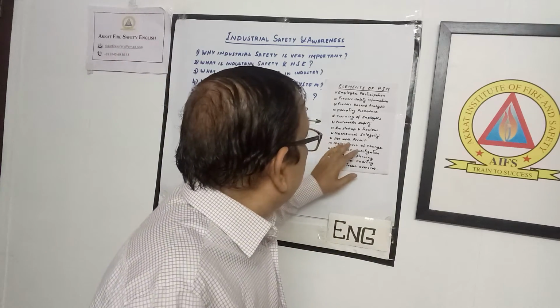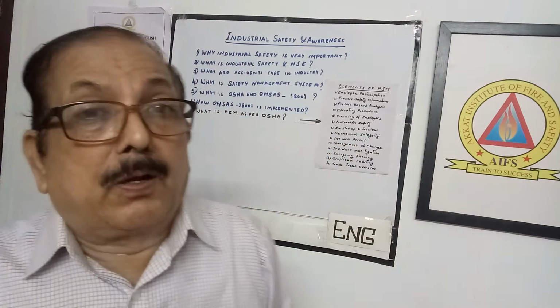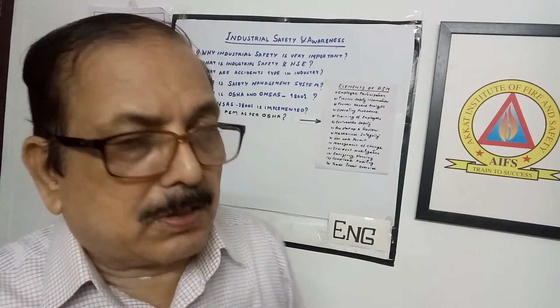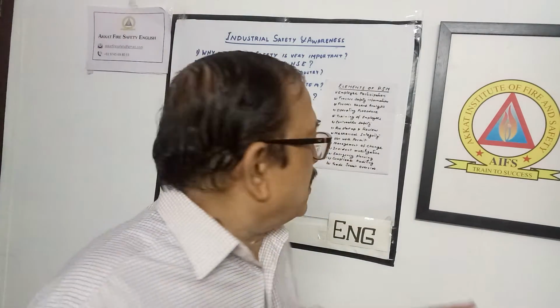Then another one is hot work permit. What do you mean by hot work? It is cutting, welding, gas cutting, etc. Because many chemicals are there in such buildings, there is a chance of fire occurring there. So if anybody wants to do hot work, they should be given a permit in the system. A systematic permit method is there. That hot work should be in a permit system.